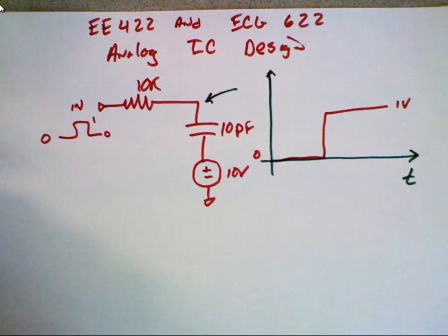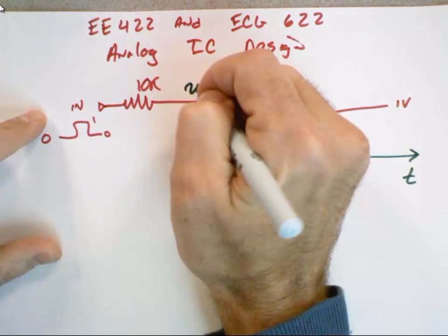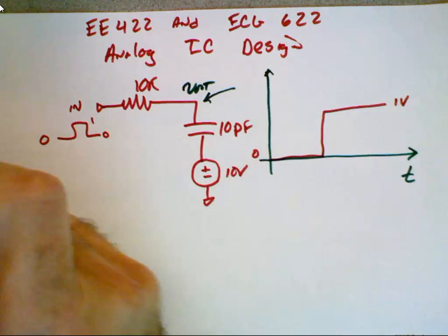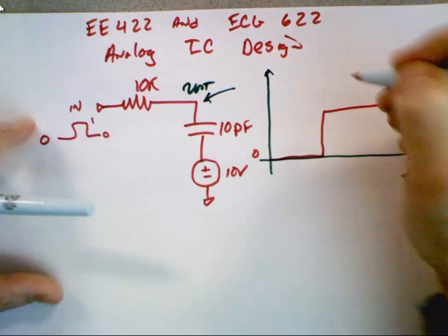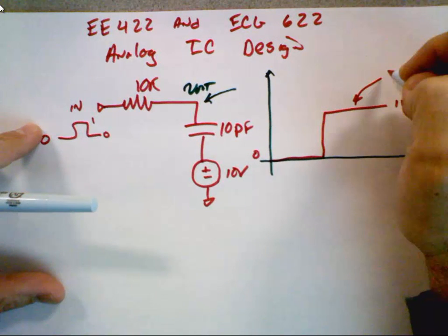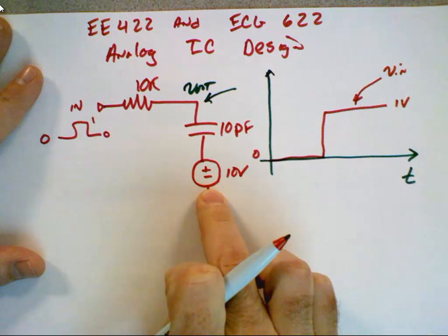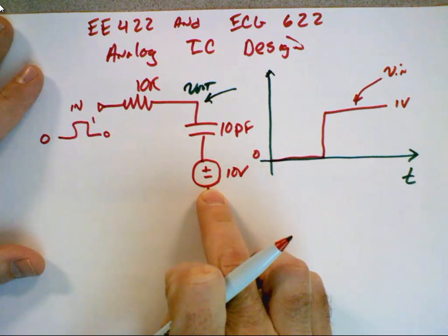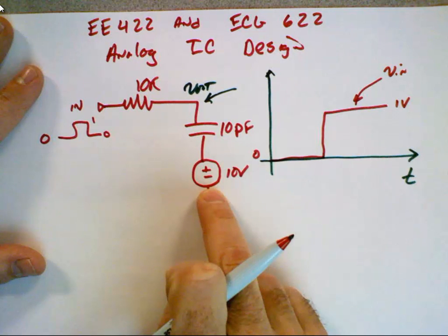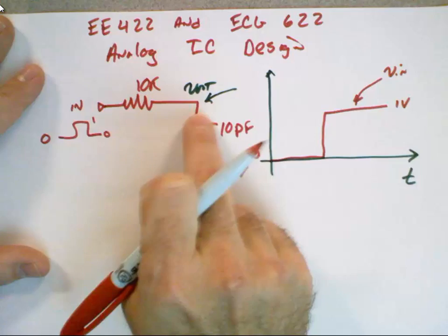This is V out. Now I'm doing this on purpose because this 10 volts is kind of what you have with the MOSFET in some of the situations on one side to keep it in strong inversion. And I ask, how does it affect the voltage over here?